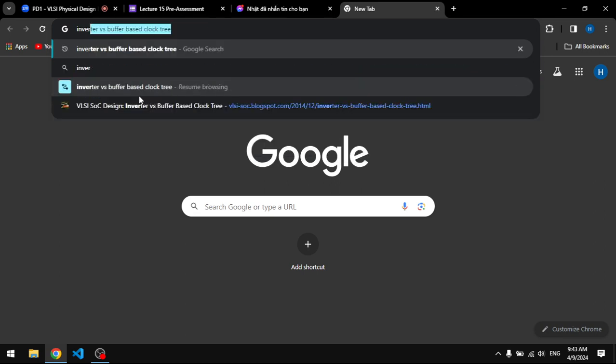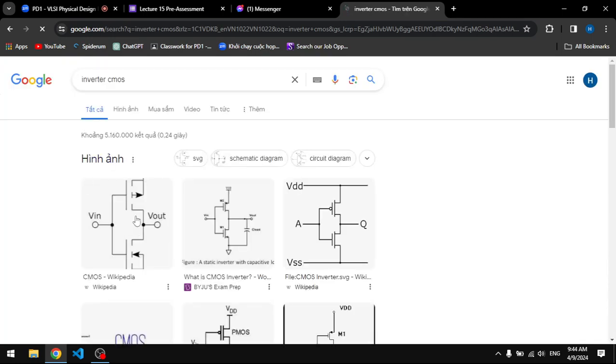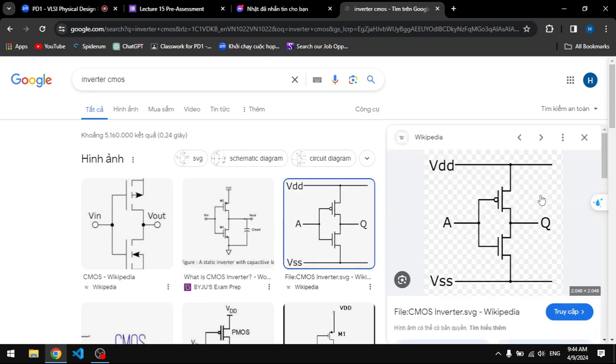But the tool will first try to meet the CTS constraint. That's the first priority it's going to meet. So yes, it could lead to congestion. That's why after each stage, we want to make sure that the congestion is still controllable, right? If after placing you have congestion, you got to go back. After CTS, if you have congestion, you got an issue. You got to figure out how to resolve that congestion.